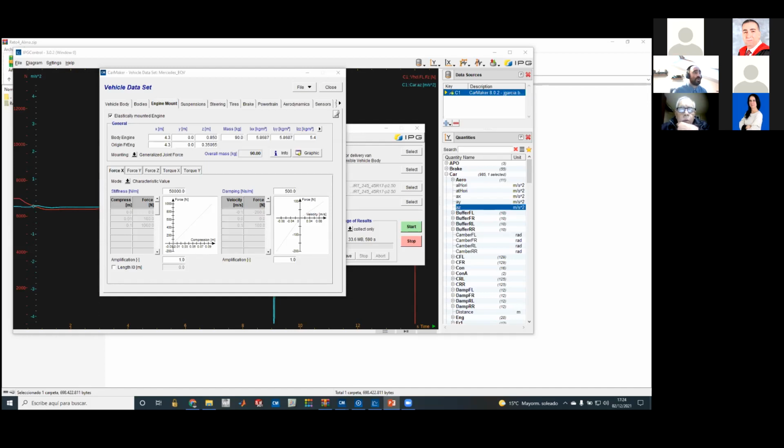So in my prior presentation, we said that the engine modes can be computed or characterized using this kind of lumped parameter systems. So the only thing I have to do is to develop a model to identify the stiffness and damping of my engine modes in X, Y, Z, and also regarding the other two torsional degrees of freedom.